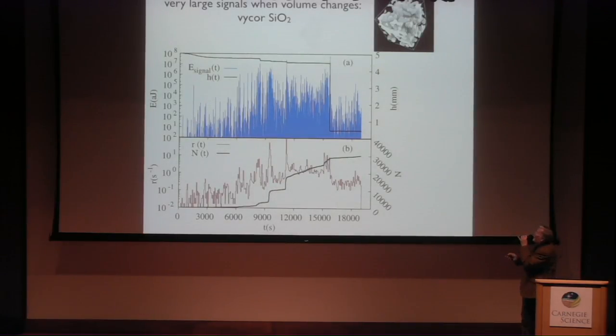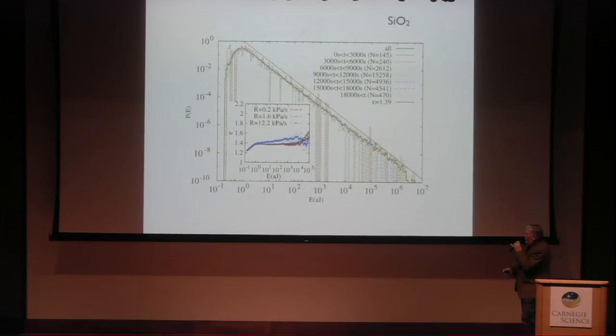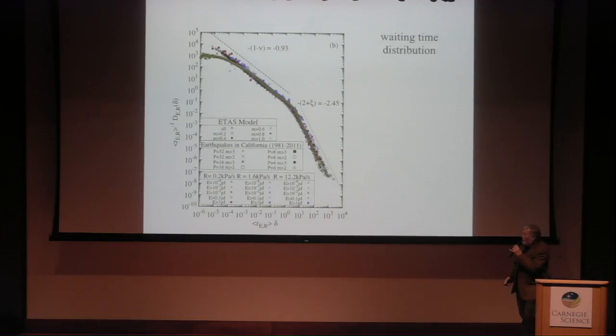So here's a typical example. You have a porous material, you do exactly the same experiment, you squeeze it. Each time something collapses, something fast happens, you get a jerk. Then you look at the probability of finding these jerks, and you can see here over 6 or 7 orders of magnitude, it follows the power law and the scale invariance perfectly, right? And now, just to demonstrate, also the time intervals between jerks are totally determined, so there are critical exponents for that.